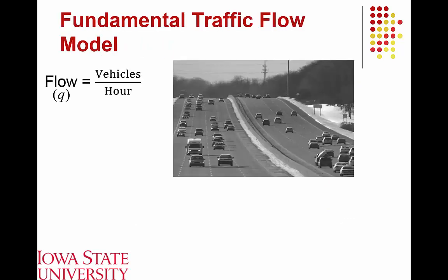Now, just wrapping up, we're culminating this lecture with an introduction to what we refer to as the fundamental traffic flow model, which is the basis of our traffic flow theory. The fundamental traffic flow model relates our 3 key traffic characteristics. First of all, flow, which is denoted as Q, which is simply equal to the number of vehicles observed during a standard time period, which is typically given as 1 hour.